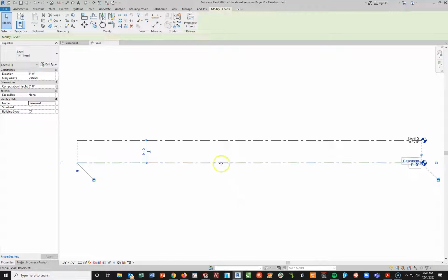So from the base of the ground to the bottom of the next floor, or basically to what I would consider the ceiling, will be about right here, about a foot below. So it should give you an 8-foot basement, which is pretty standard unless you're in a really high-end home. Then you may get a 9 or 10 foot. But remember, the height you add on costs money.